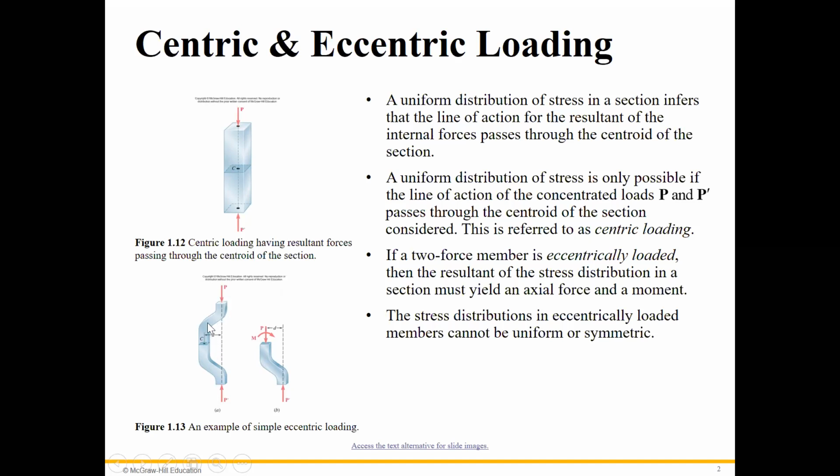If you make a section at any point in the first one, we have just the axial force. But here, if you make a section at this point, since there is an arm or distance between the force and this point, we have an eccentric loading, which means we have a moment here.